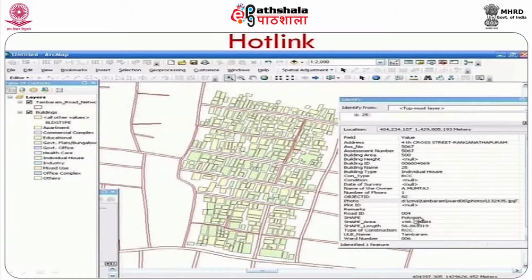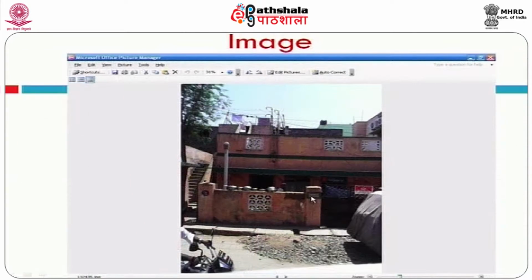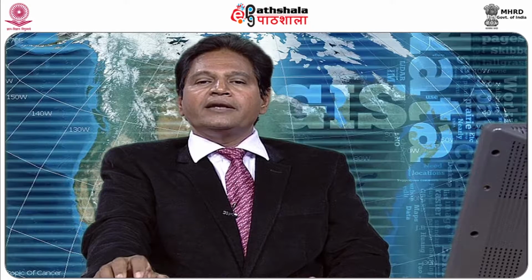Let us not go into the details of that, just to give an idea. In fact, I was just telling you, there is no limit for the number of fields. You have n number of fields here, but you also have one thing called the photograph. You can see here a hot link which is shown here, a simple lightning like indication. This hot link is indicative that this particular land parcel which I have selected is linked to a photograph. You see, by clicking I will get the photograph of the house. So, hot link will be very useful when you want to bring real world features into GIS environment.